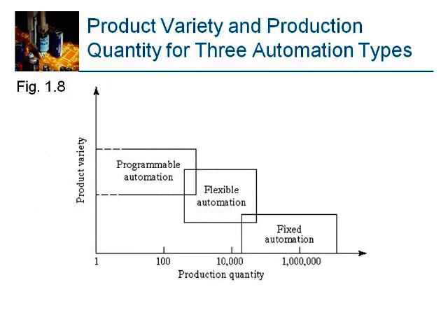The PQ diagram discussion continues. For mass production systems, where the production volume is more than 10,000 components with product variety equal to 1, we can go for fixed automation. Completely mass production systems can be done by fixed automation manufacturing systems. Coming to the other end, where you have job shop systems, we can implement a job shop as a programmable automation system. Programmable automation equipment can be incorporated in a job shop environment, where the job shop is altered to a programmable automation unit to enhance the overall production capability, including the variety.